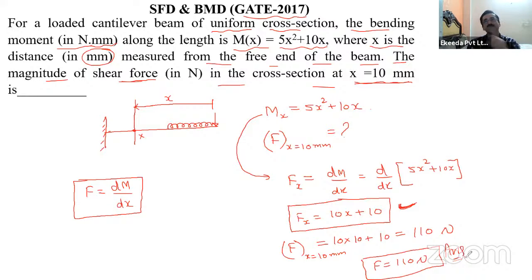So for that, you should know how to find the shear force and bending moment at a section. And the most important thing is to find the maximum bending moment, because most of the failures in a beam take place at a section where the bending moment is maximum, because the bending stress is maximum there. Although shear stresses are very small compared to bending stresses, most of the failures take place due to bending stresses, but we should know how to find the shear stresses also.